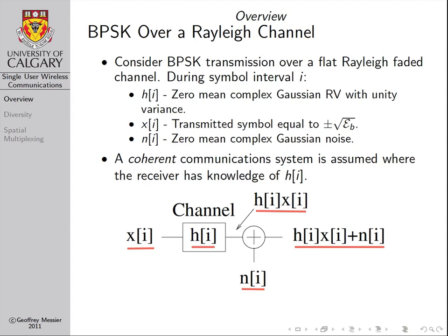In many ways, this is very similar to the received signal that we had when we looked just at the additive white Gaussian noise channel. We have some received information symbol corrupted by additive Gaussian noise. And in that case, we saw that the best or the optimal way to deal with the received information was to use the matched filter.